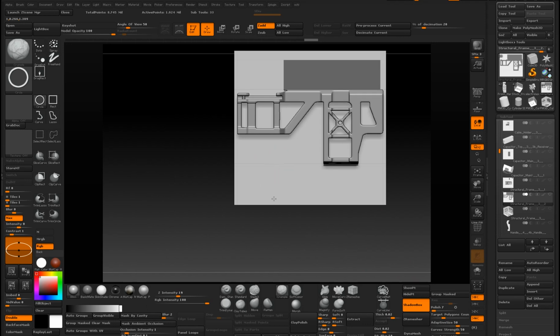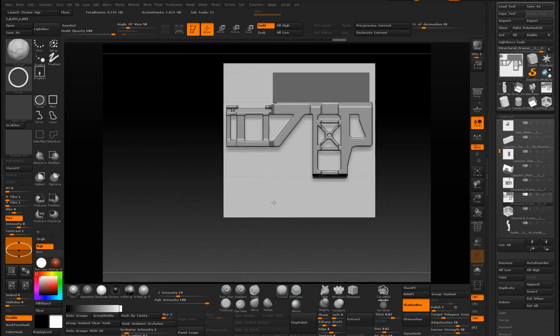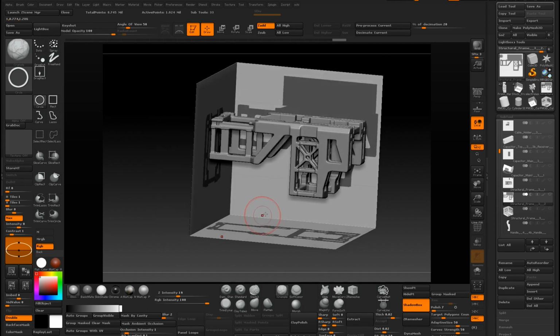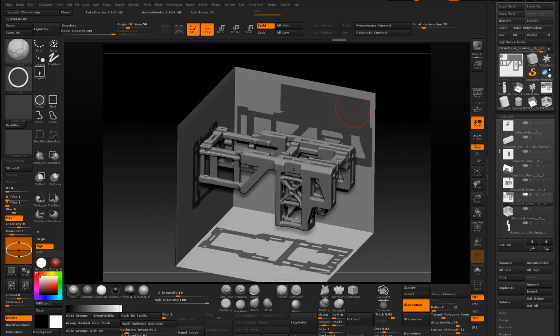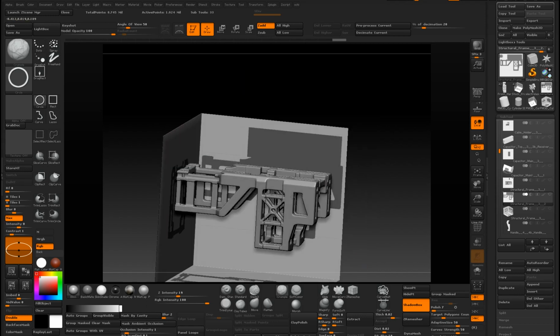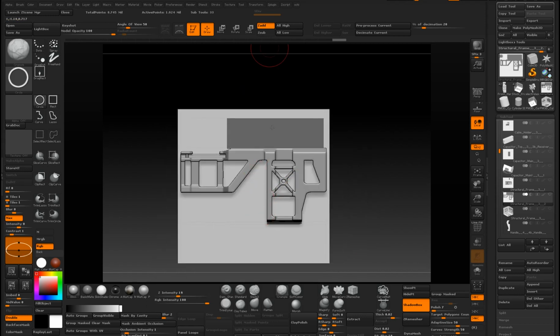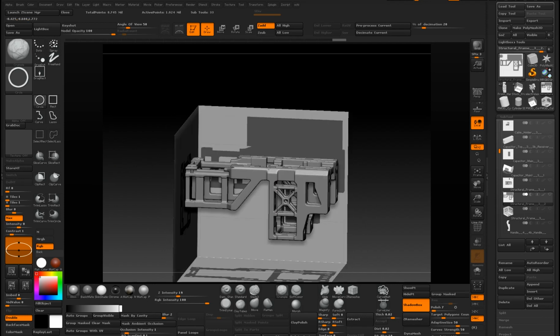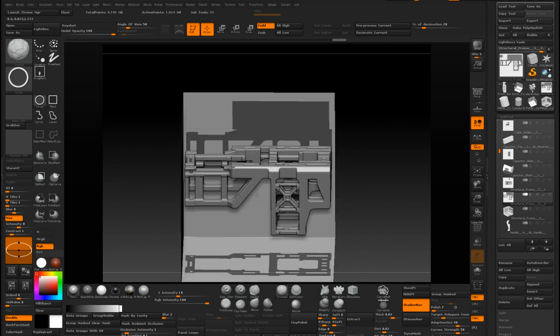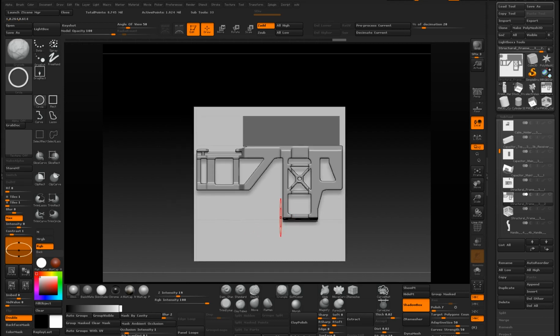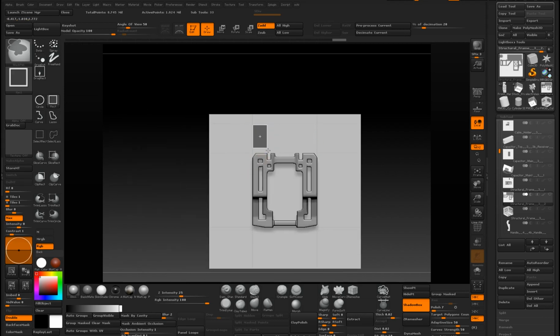If you create a little cube there, it won't be subdivided like a normal subtool. It just subdivides the whole box. And that kind of limits you to this square design, so you cannot really make something super long or super thin. I'd say it's a pretty big limitation. But yeah, something to keep in mind when you design.